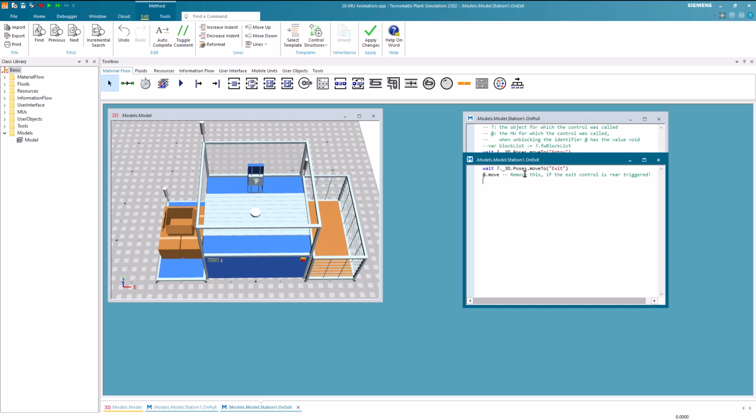Since we want to move the slider to a specific position, we subsequently need to access it instead of the poses. And to access it, we can use the getObject method. As parameter, we need to pass the index of the object we want to access. Since there is only one object that we have created, we simply enter one. Using an index for performance is a more efficient approach, while an alternative method involves using the animation object's name, which, on the other hand, offers greater clarity.